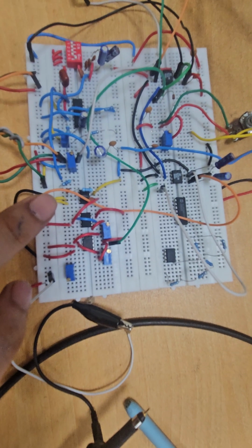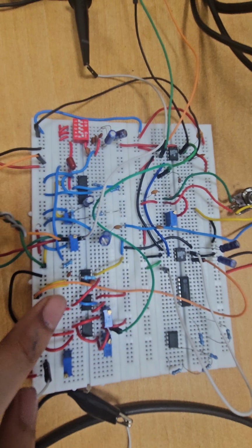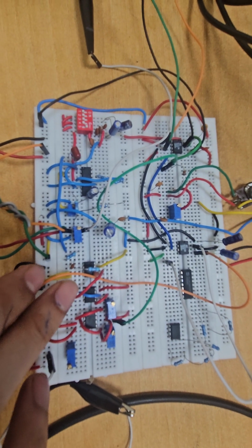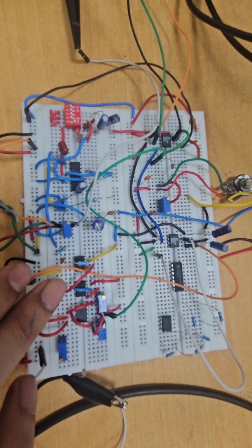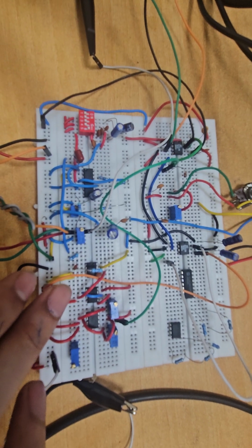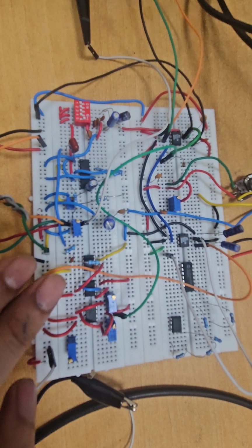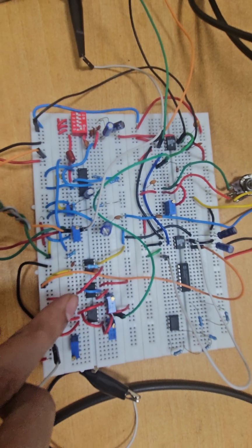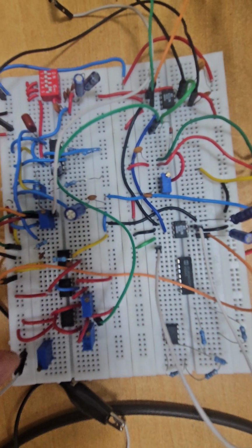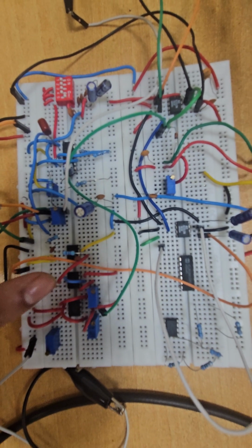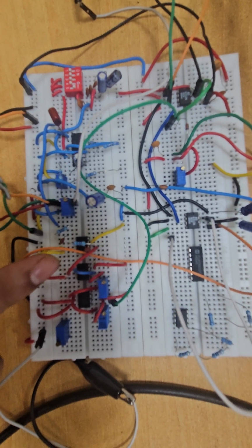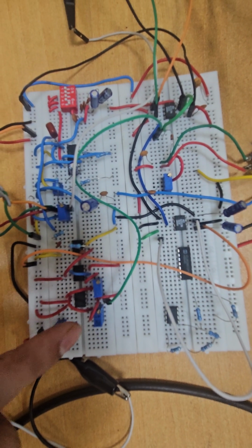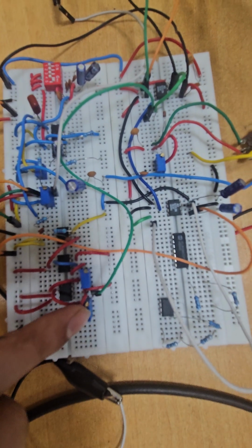So we can operate the band pass filter as a differentiator at the rising edge of the transfer function. Now after this, I have implemented one buffer. Also the gain of the band pass filter is very low, so to amplify the signal, I have used one inverting amplifier.